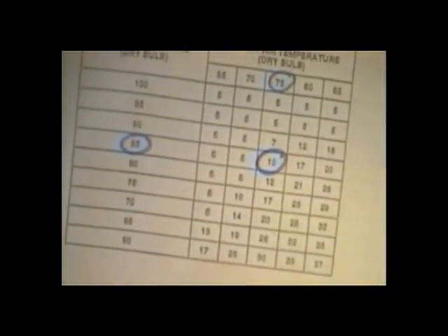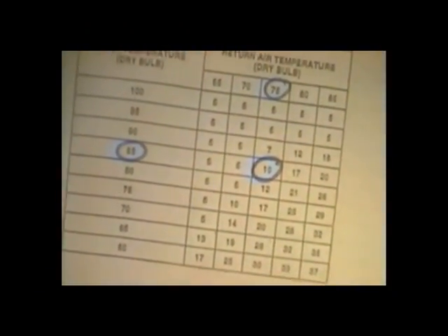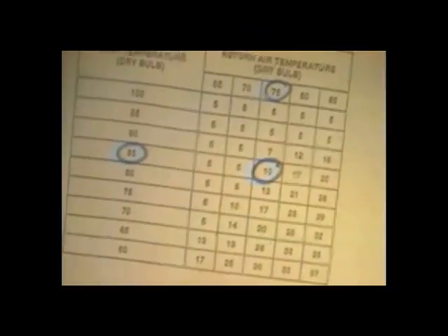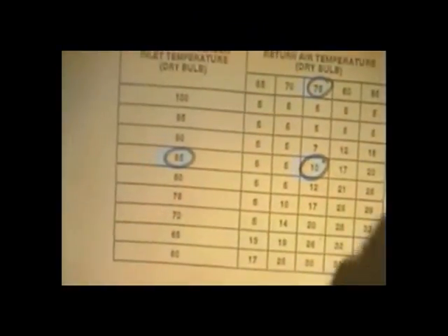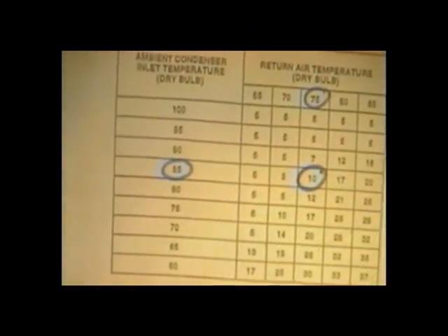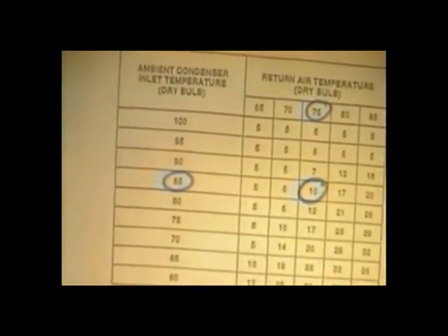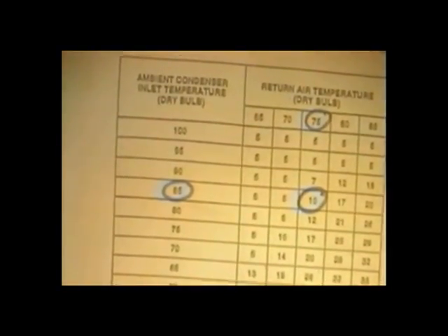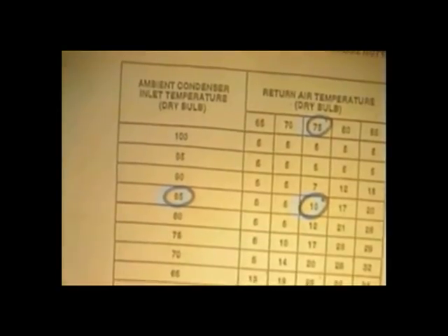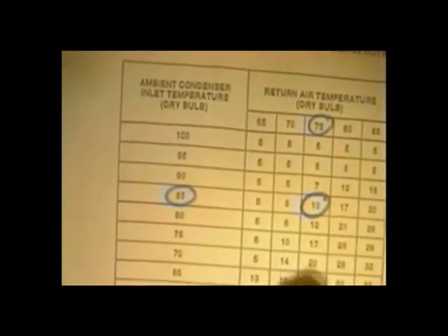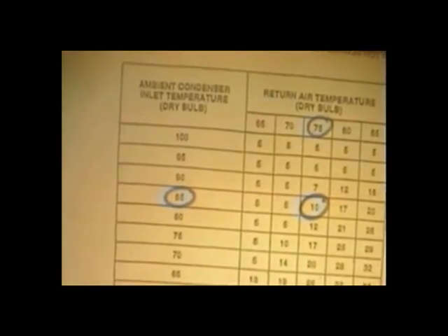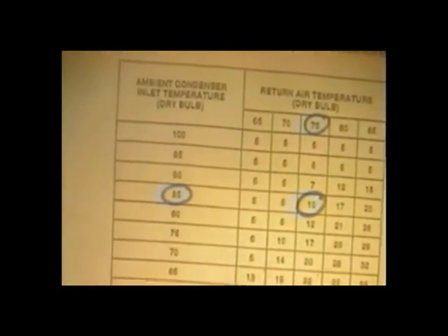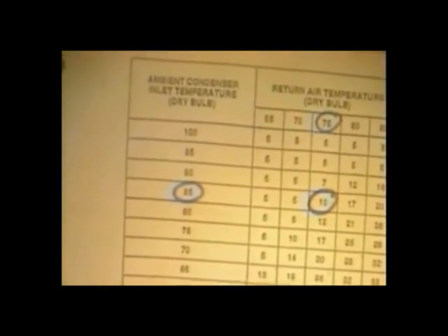See, now you got to go back and say, oh man, I got to look at the chart. And it's too high, that's right. All right, and again, only for purposes of conserving time, because we're doing a video, remember, if the superheat is 20 and you want 10, well, you need to lower it. And you lower it by adding gas, okay? But if the superheat is too low, you got too much gas in there, and maybe you only got 5 degrees, then you want to recover. We don't vent anymore, we recover refrigerant, okay? All right, that's one example.